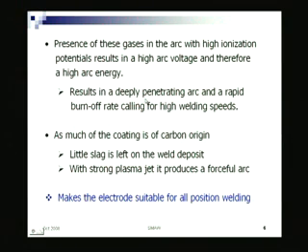That results in a deeply penetrating arc, which means a cellulosic electrode is used where you need a higher penetration, depending on the plate material to be welded and the situation, because you know how much the weld fusion will be. The penetration means this depth of fusion.